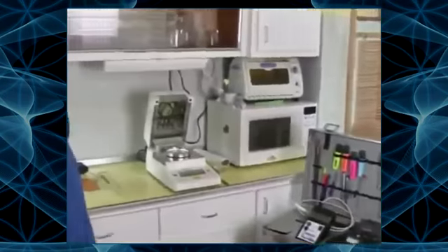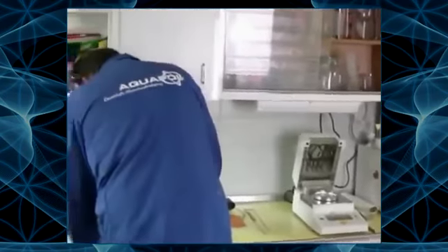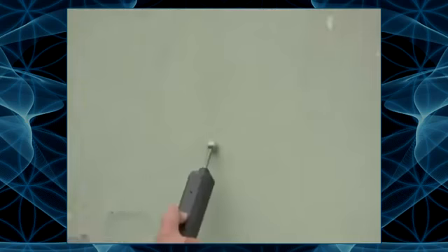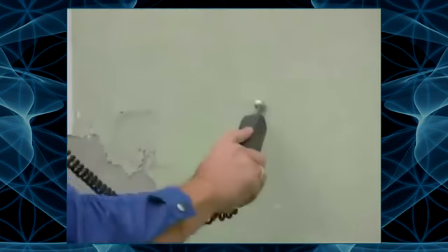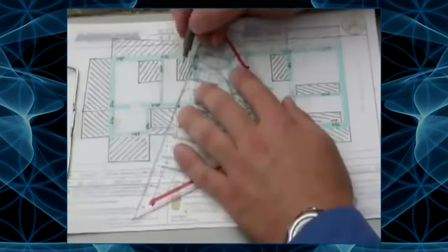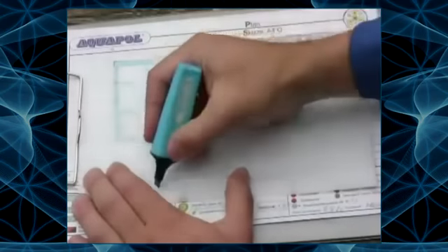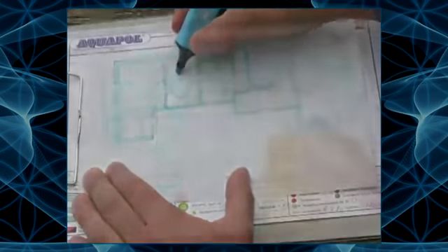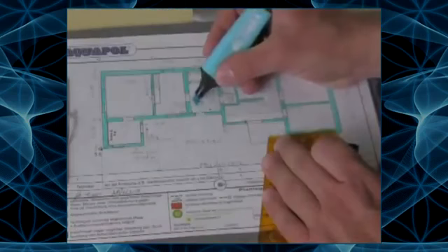Before the installation, the technician performs diagnostic investigations of masonry using the appropriate measuring devices. He determines capillary heads for the entire building and draws a capillary head diagram. Geological influences on masonry moisture and other important details are noted on the plan.